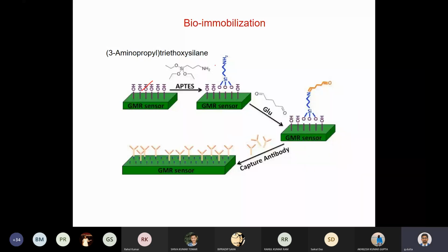First you can form some carboxylic group on your sensor surface. How can we form carboxylic groups? You can use carbon nanotubes already functionalized with carboxylic acid, and you can drop them or print them on the surface. Then you will get a carboxylic acid group surface. Sometimes you can also oxidize the sensor surface to get the carboxylic acid group. So some carbon-based material that contains lots of carboxylic groups can be used.